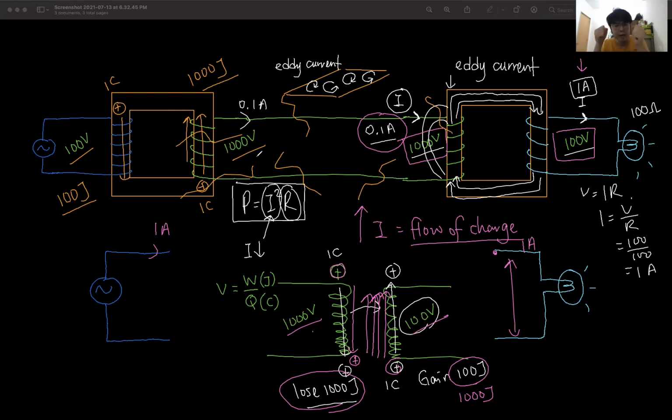Because the voltage is so high, it can pull the charged particle away from the atom in the atmosphere. Okay, so as a result, you see lightnings. So that's why there's a limit. Okay, there's a limit. The point is there's a limit to step up the transformer. Now, in the generator, the power plant, they step up to very, very high voltage. Very, very high voltage. How high? Like a few 100,000 volt. Okay, a few 100,000 volt.